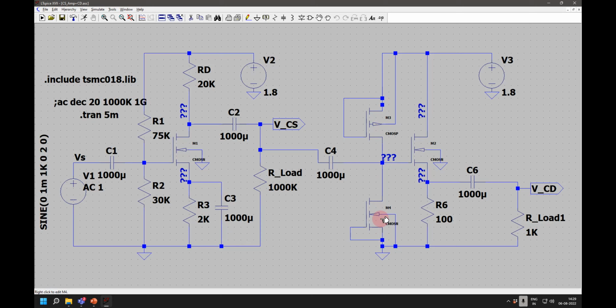So how does that help? If we remove them completely, what does it alter? No. These 2 will act like resistances, even though they are off. You have to consider them as mega ohms resistances. So that will get my DC operating point here between VDD and ground. It is like connecting a 100 mega and 200 mega here and getting the desired voltage here. Okay.